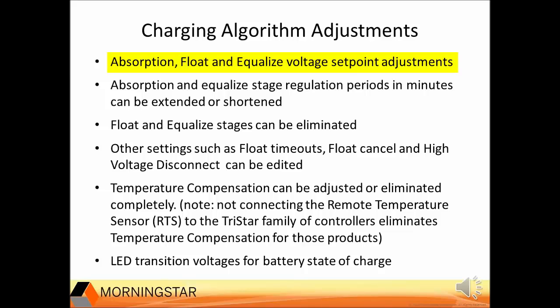So if you have a 24 volt battery, it multiplies the voltage by 2, and it will show that in the column for 24 volts. And if you're programming it for 48, you would still program it for 12 volts, and it would just automatically multiply by the 12 volt nominal setting. So every setting you make has to be done in 12 volt or the multiple of the voltage that you want to set it for.